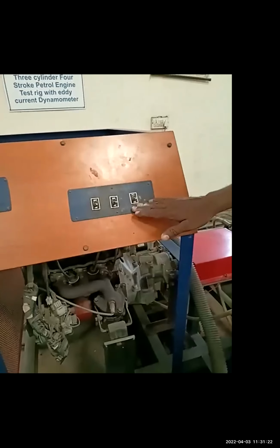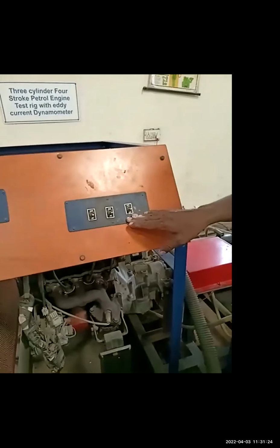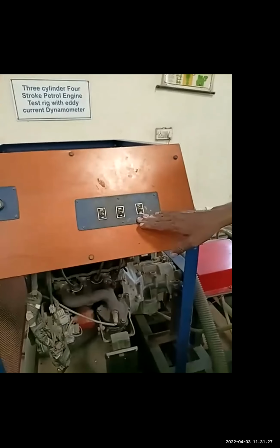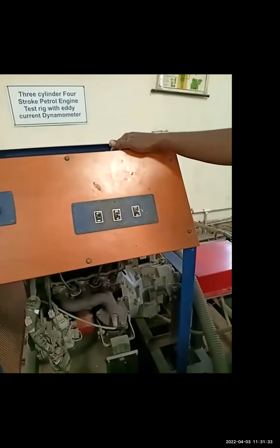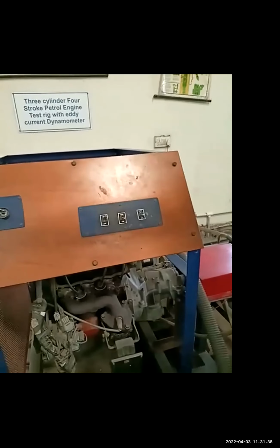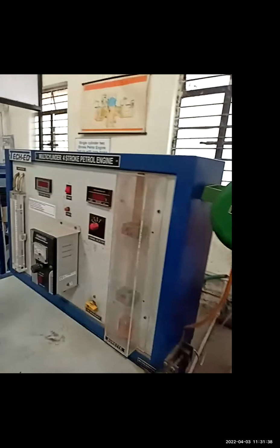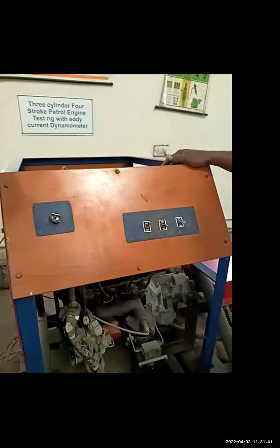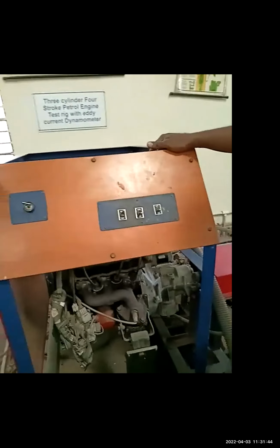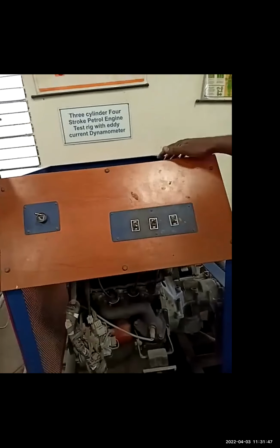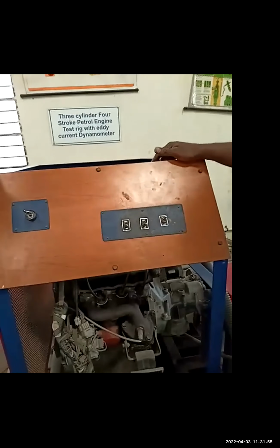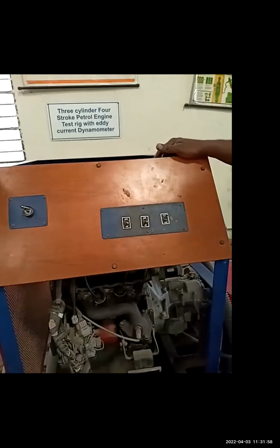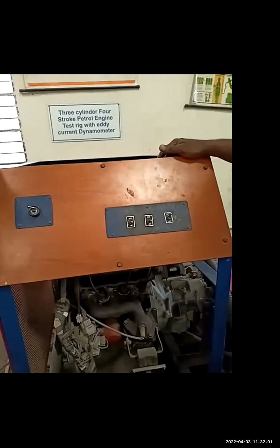If I run with all the 3 cylinders on, I am going to get this B, the total B. When I switch this off, cylinder number 1 is cut, I work the engine and measure the power. What I get is BA, the power of the engine when cylinder number 1 is cut off. I switch this on and switch this off, so cylinder number 2 has been cut off. Now I measure the power once again. In the third case, I switch off the spark plug of cylinder number 3, and once again I measure the power. So 4 times I have measured the power.